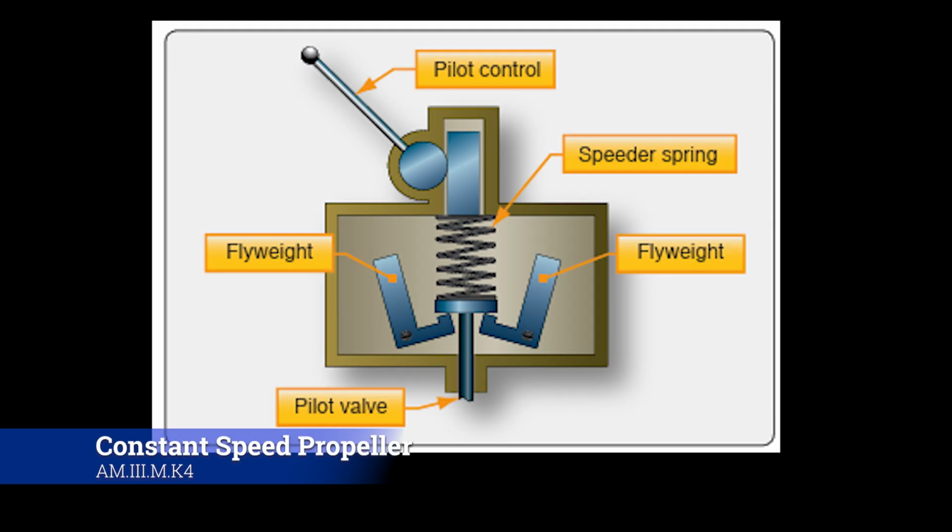Now, I think about it, as the blades start to turn, they're grabbing more and more air, so that pressure is coming up higher and higher. That way, it's starting to naturally slow it back down. As it starts to slow back down, you'll eventually get back to an on-speed condition.